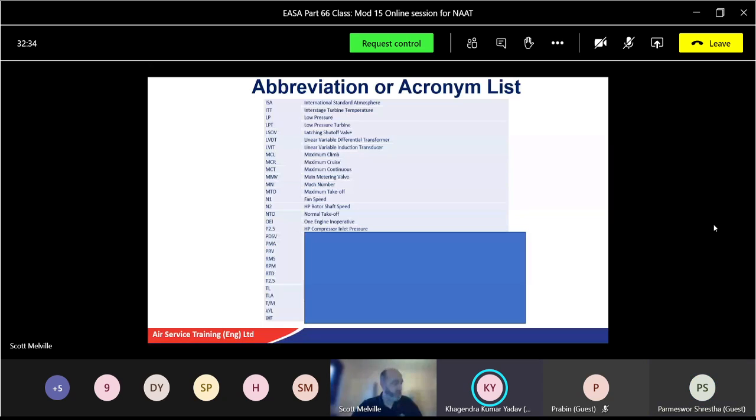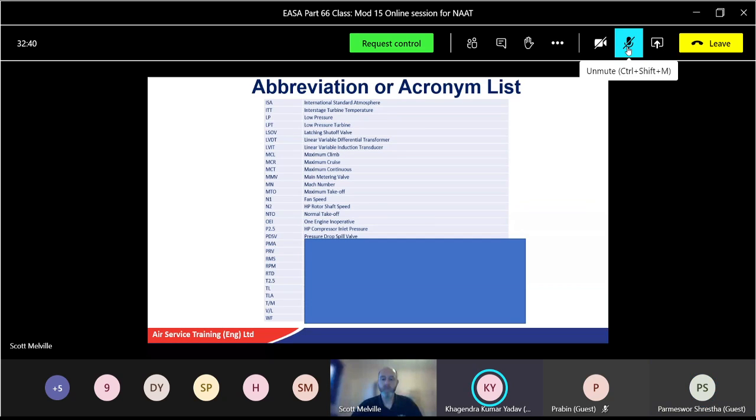Okay, PMA. Think electrical power. Electrical power for the FADEC, permanent magnet alternator. So I'm good. For a bonus point, when does that activate? At what speed or what RPM or percentage of RPM? 50%. 50%, good man. Good. See, it's all coming together, isn't it?